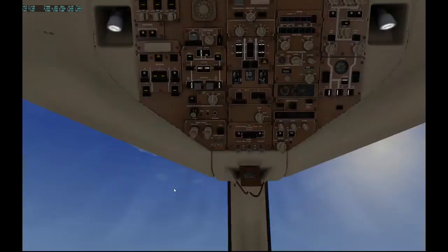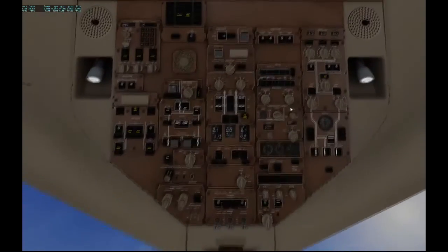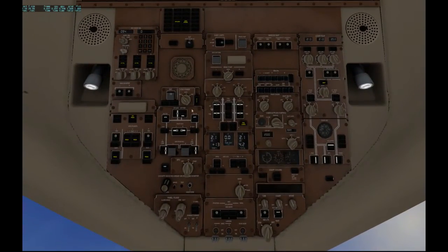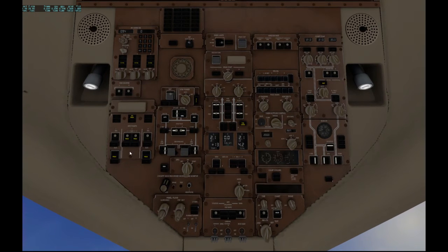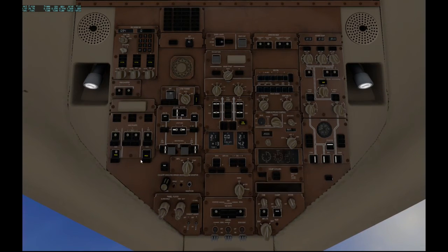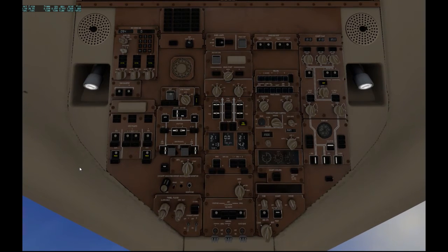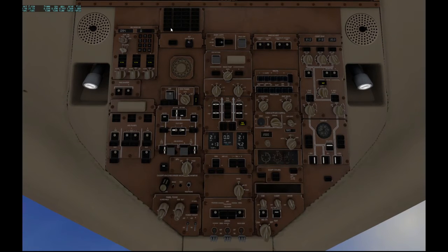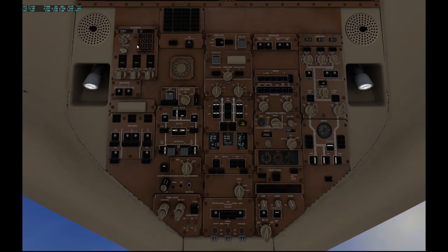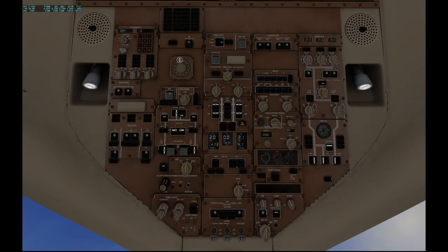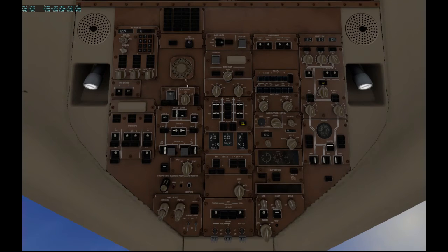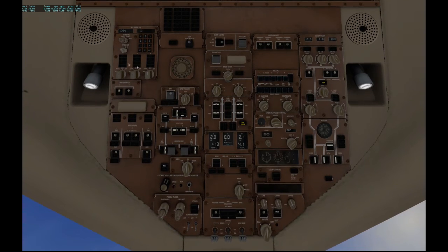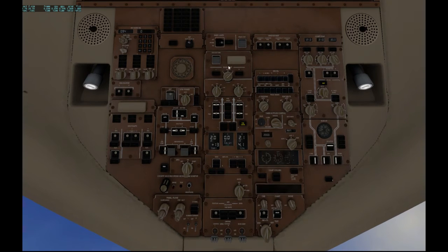All right. Let's look at over here. Now that we got the engines going, we can go ahead and turn on all the hydraulic pumps, all the electrical ones, left and right. And annunciator panel up here is clear. Let's go through our flows again. Well, that's good. That should have been an auto. I can't believe I actually missed that. This is all good. Those DC fail lights are off. This is all good.